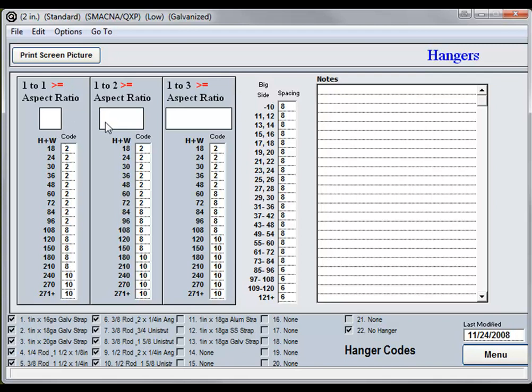If we look over here, we're looking at 1:2 aspect ratio, or rectangular ductwork. 1:2 would be, say, 12 by 24. And if we look at the next column, we're talking about 3:1 ductwork, so this has a ratio of 12 to 36. So basically, we're going to start with the 1:1 aspect ratio.